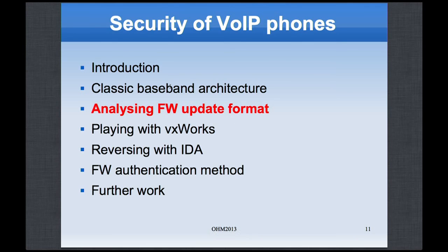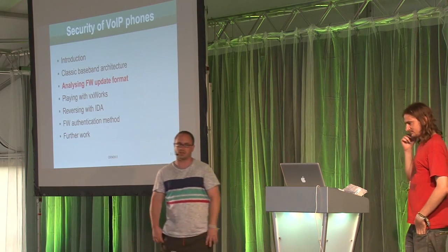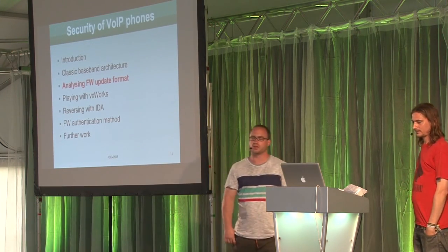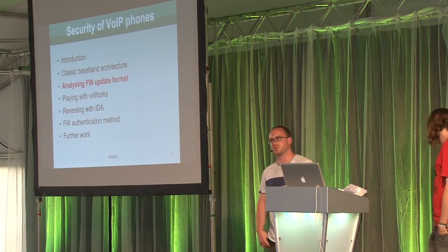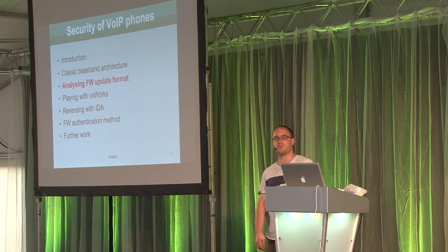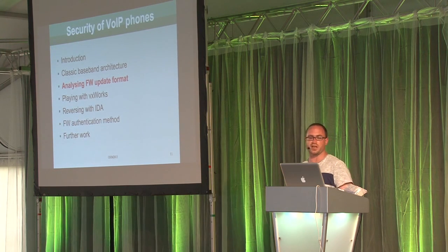So I will talk now, hello everybody, about how to analyze the firmware update format. We will manually use some standard Unix command line tools like xxd, strings, dd, and file. These tools will help us for the beginning.